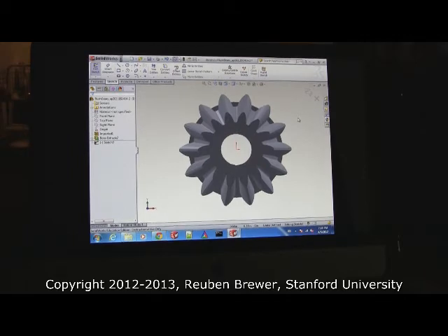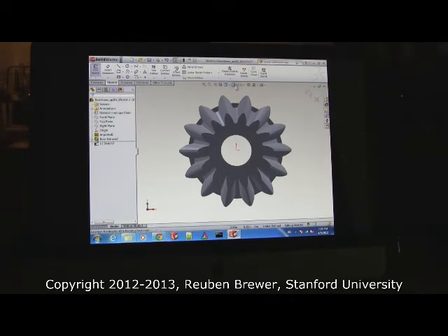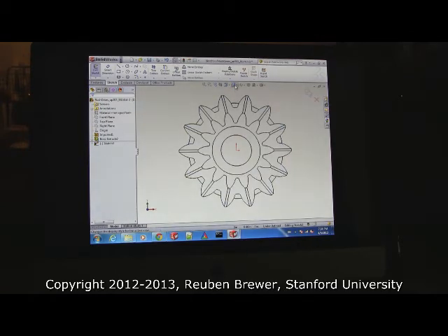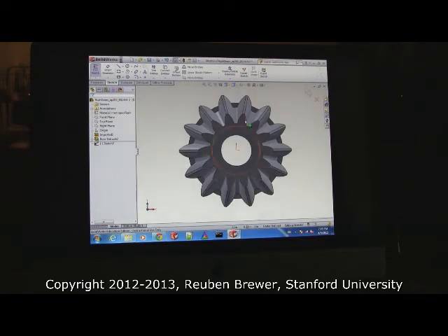There are different view modes in SolidWorks. Everybody look at my screen. See display style? Right now, we're in shaded but no edges. Here, shaded with edges. Hey, I can see my circles. I could also do wireframe, all types of wireframes, hidden lines, no hidden lines. When you do shaded with edges, it slows down your computer. For a few parts in an assembly, it's really not a big deal. So let's leave that on.